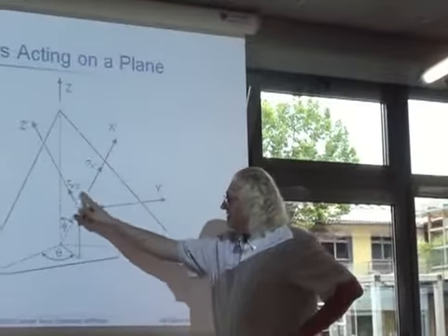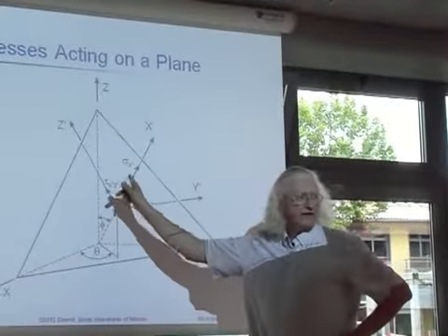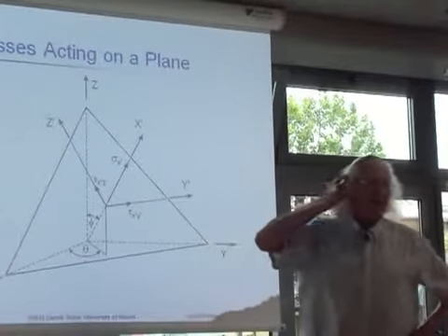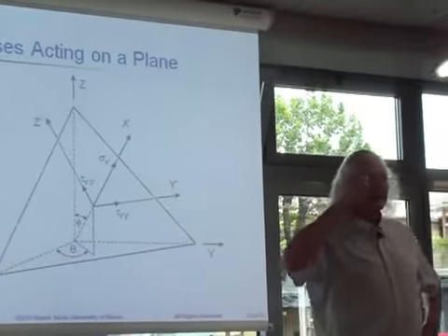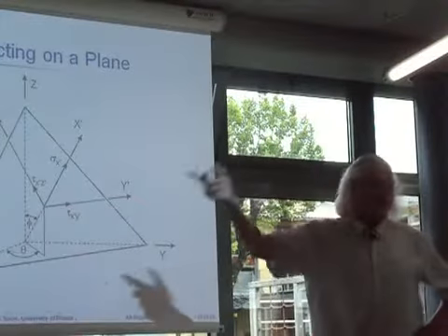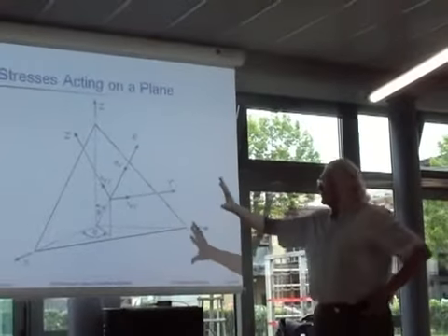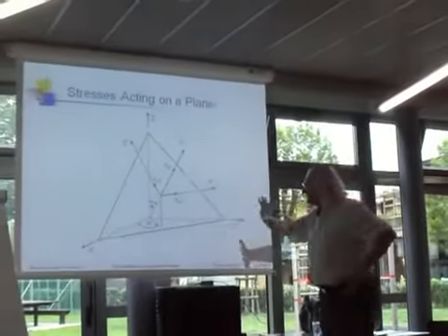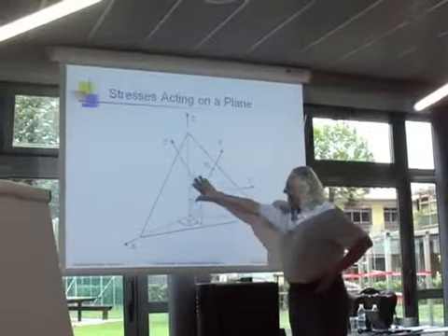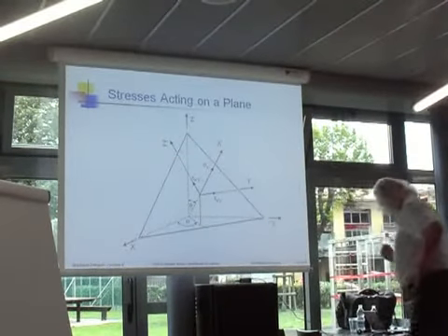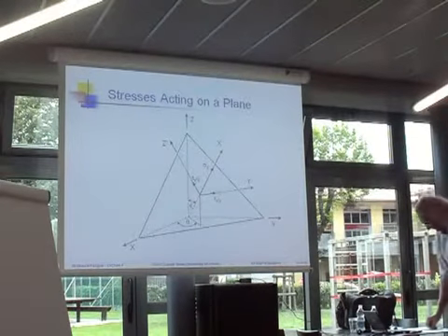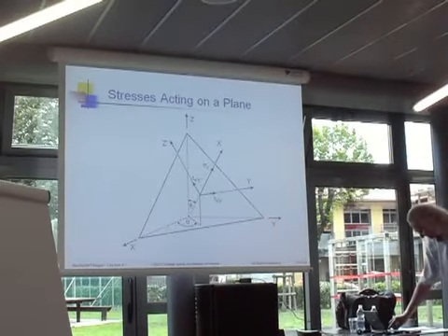But if we wished, we could combine this into 1 shear stress. And that's essentially what happens when you calculate the equivalent stress or Mises stress. You essentially combine both of them. So these are the driving forces for fatigue, the stresses that act on the plane. And I say there are only two or three of them.